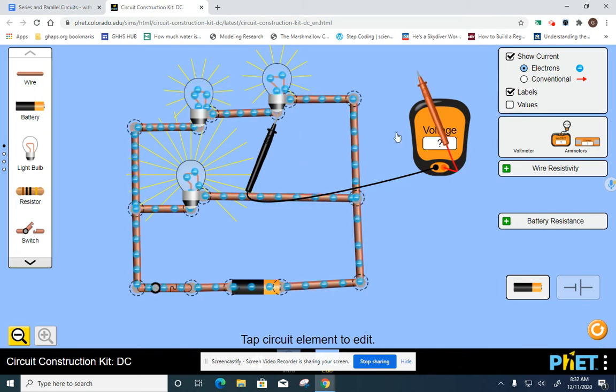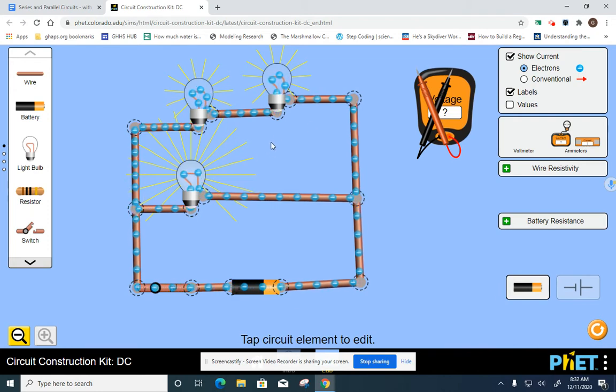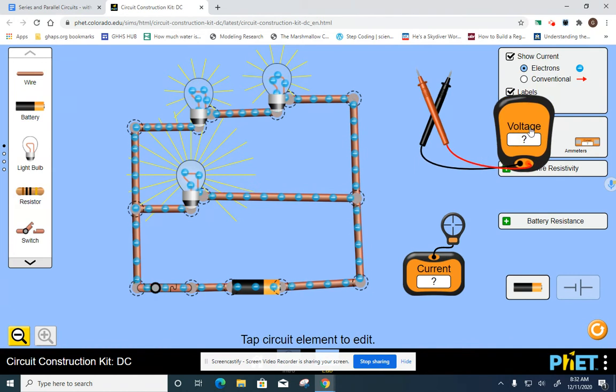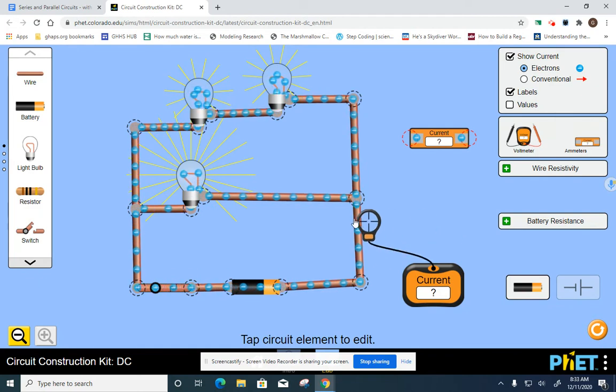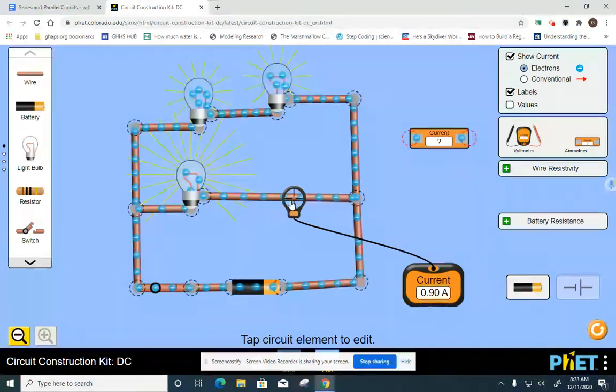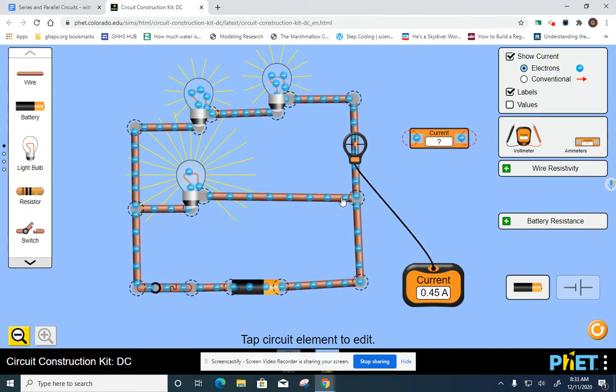Okay, so the voltmeter is pretty easy to use. A very non-invasive kind of measurement. I don't need to modify that circuit at all in order for me to be able to measure voltage drop across the device. Now, there are 2 different kinds of ammeters that I want to show you. One of them is a very simple ammeter to use. It's very non-invasive, sort of like the voltmeter. I can just place this thing across that wire, and the charge would be flowing through that hoop. And through a process called induction, that's a topic for a later lesson, we can measure that current with an indirect measurement. I don't need to actually insert this thing into that wire.